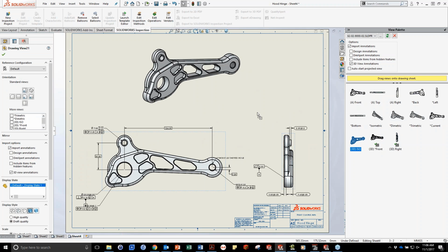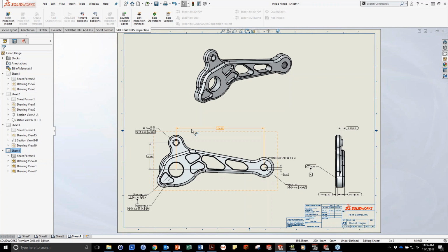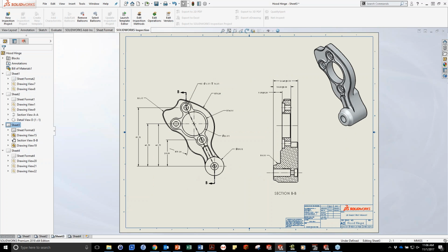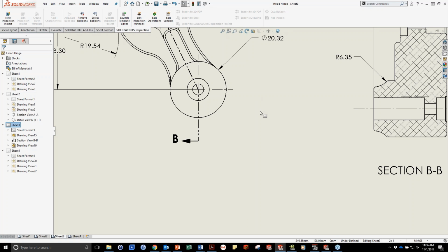If you're doing something twice in SOLIDWORKS, give us a call. Now that looks pretty good. It was fast, but all the traditional drawing tools, of course, they're getting some more power as well. How about in the last year? Has anybody used that advanced hole wizard? I hope you have. This is that hole wizard that lets us do multi-stepped holes. You can do a million counterbores at either end of the hole, really make something complicated in one feature.